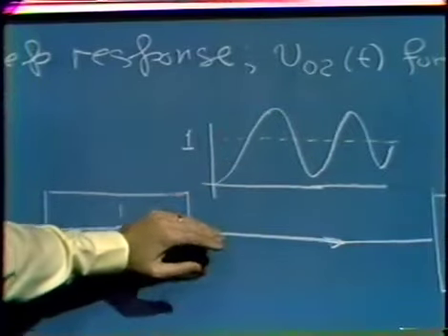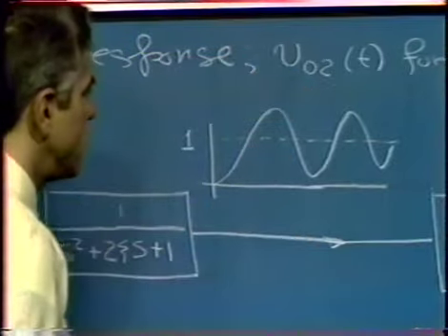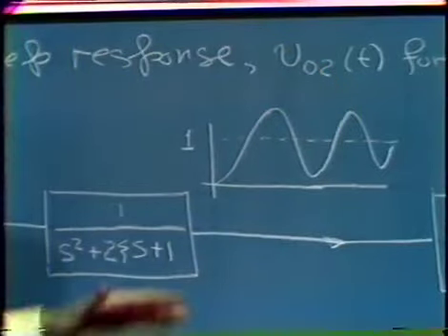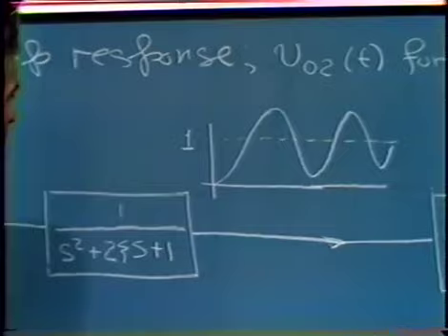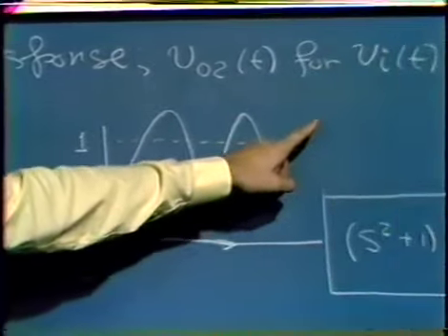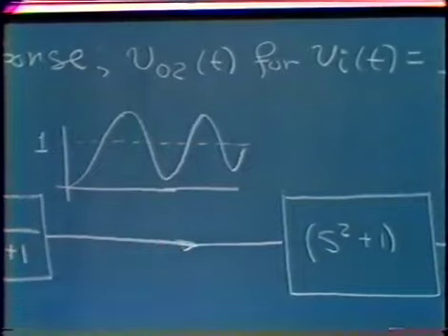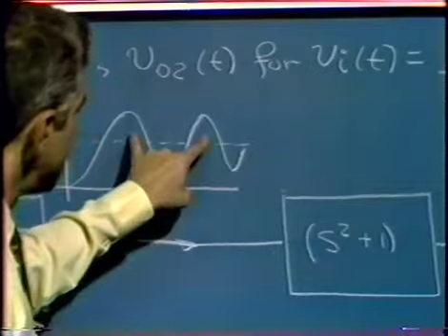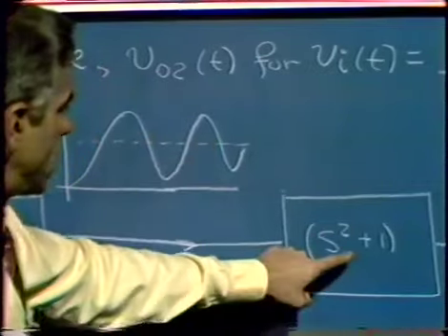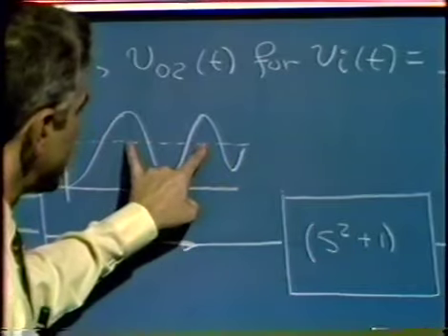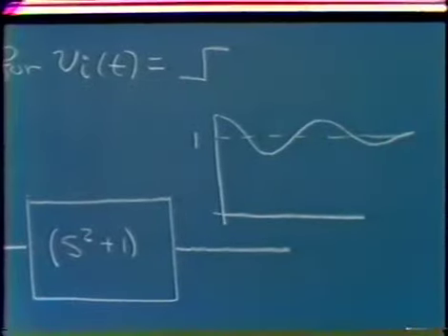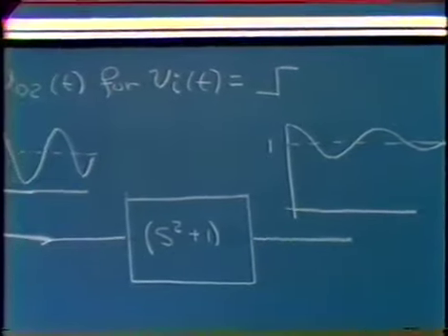And as the damping ratio gets smaller and smaller, the rate of decay of this waveform gets progressively slower. We have more and more cycles of oscillation before it dies down to a given amplitude. We apply that signal, which is very nearly a sinusoid with just a small amount of damping, to a pair of zeros which are located at very nearly the frequency of this natural response. We have a pair of zeros located at a frequency that's very, very close to this frequency of oscillation. The net result is they very nearly cancel out the amplitude, or attenuate almost perfectly the amplitude, of this oscillation.